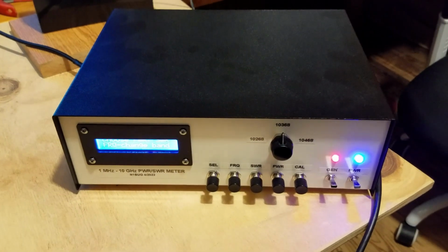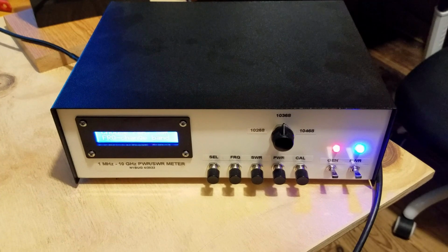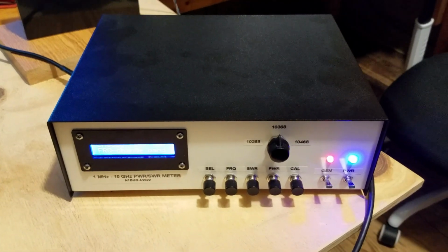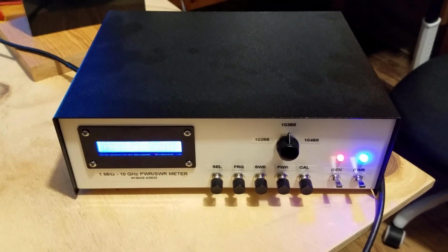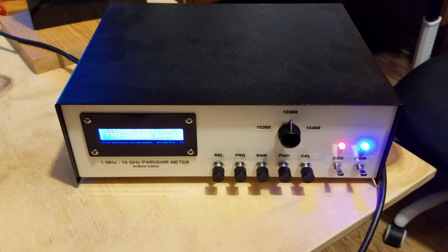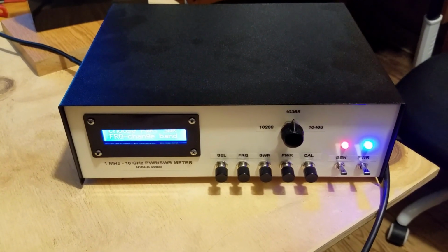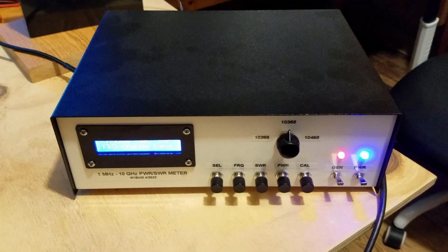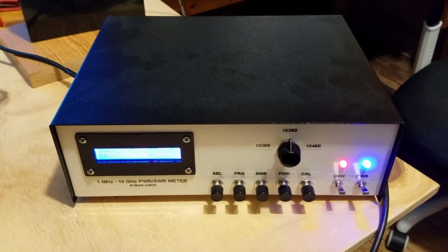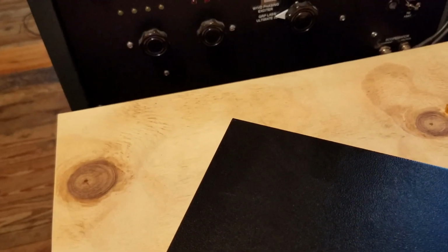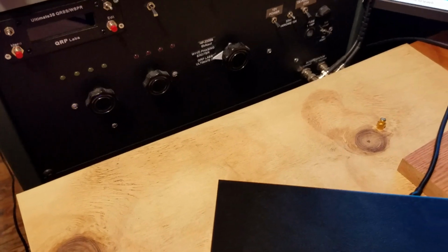Okay, so just one final little experiment here in this video. This is a piece of test equipment I built a couple of years ago when I was getting started on this 10 gig journey. This was intended to be an RF power meter and return loss bridge, and also a simple signal generator and portable backyard beacon. Inside, this uses one of the VHF design PLL boards that I talked about as a potential beacon exciter in another video.